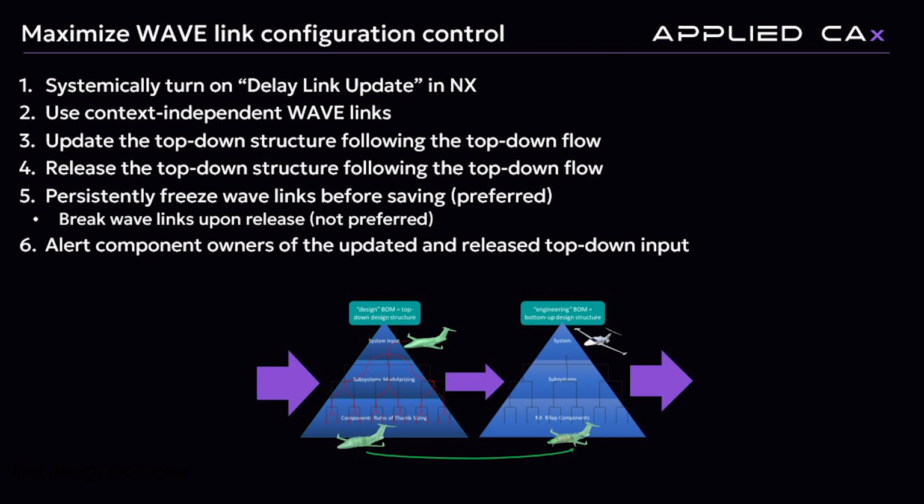This is a big tip that I haven't always thought of, because for some of the assemblies it's not as necessary if they're not very large: context independent. This is basically not transferring the position of the component. It's just the geometry.